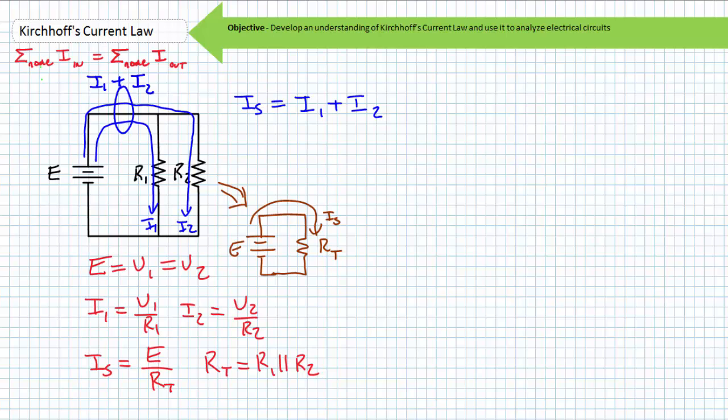Again, I cannot express how critical this step is to performing series parallel circuit analysis as we progress through this playlist. This technique is visual, reliable, and powerful. Current through elements in series is the same. Voltage across elements in parallel is the same. KCL is the method you use to determine if elements are in series or in parallel with one another. The point is, you don't need to solve for things you already know via basic circuit properties.